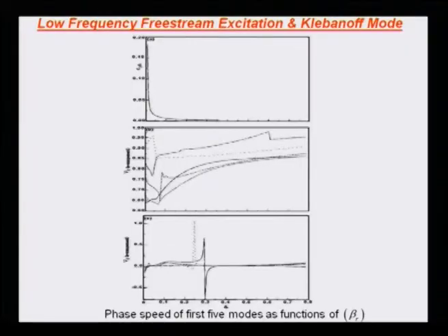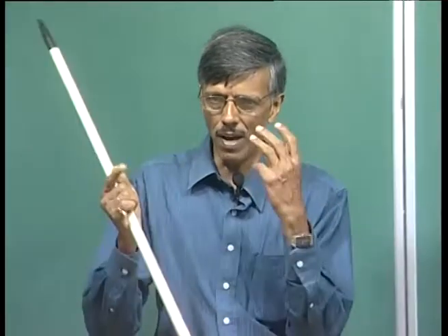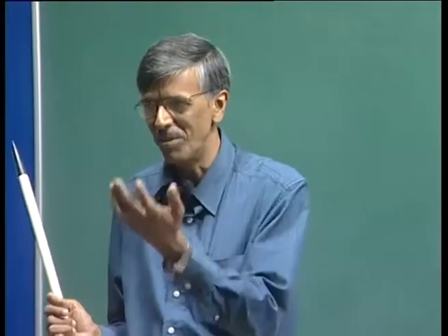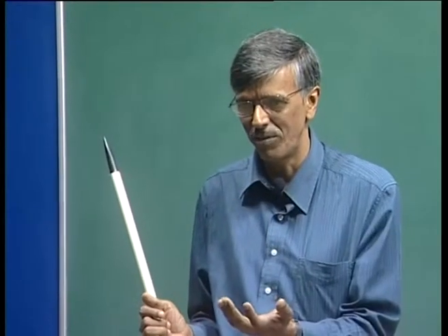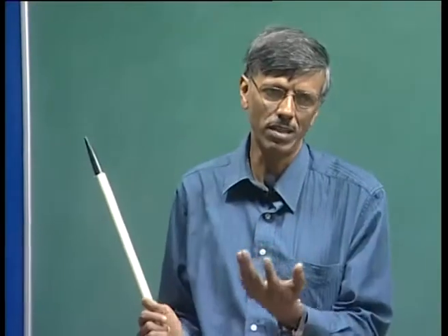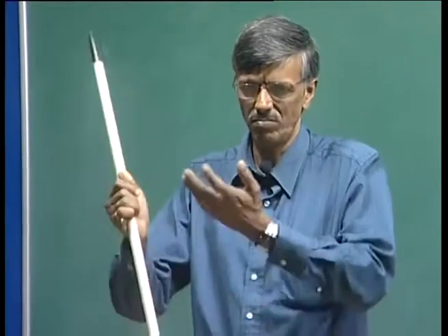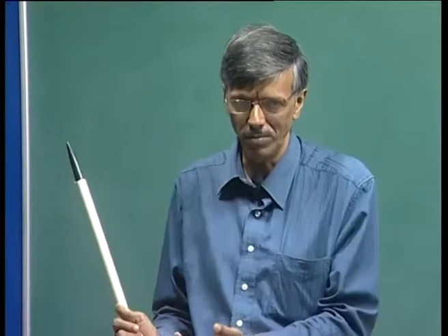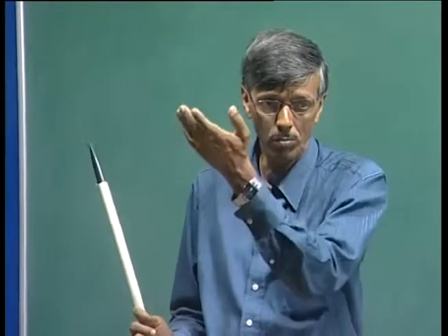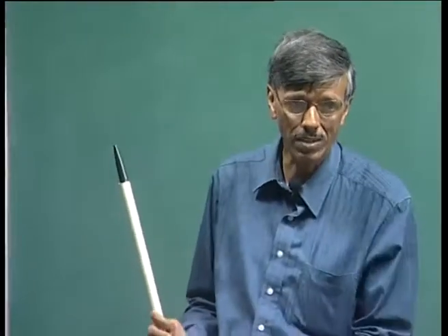So, it would appear as if the whole thing, if I look at that tunnel, the phase is not moving. So, it would appear as if it is stationary. That is what was giving us the impression of a breathing mode. We are having a 3-dimensional flow field, but C phase is virtually 0. So, we are seeing as if it is staying in the same place, but with time, because it is changing with omega naught. We have fixed omega naught. So, the whole boundary layer is heaving with that omega naught.